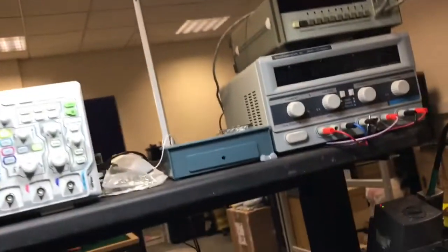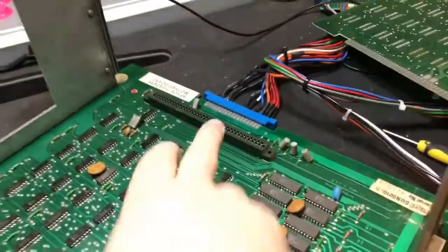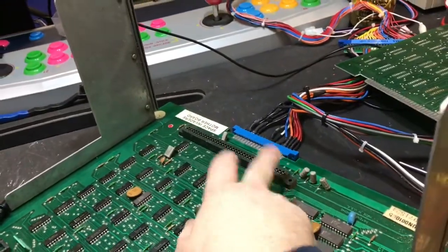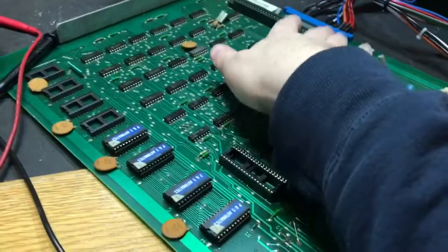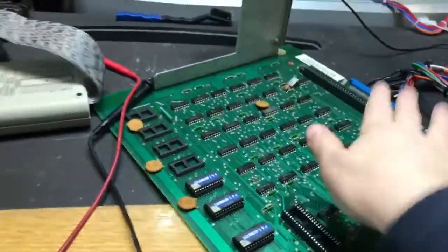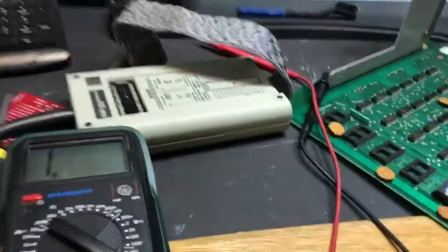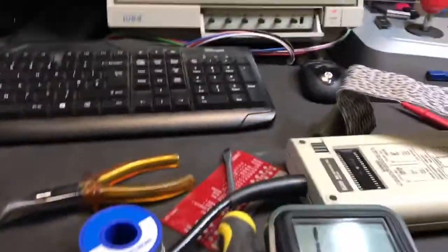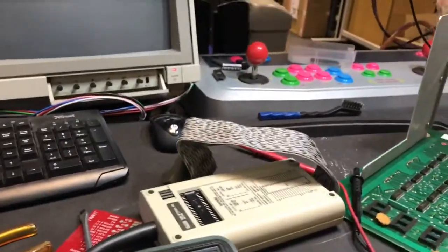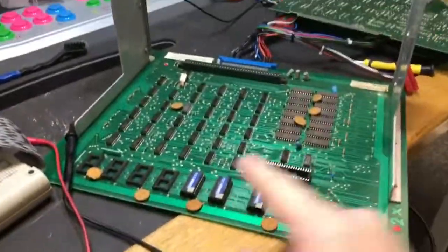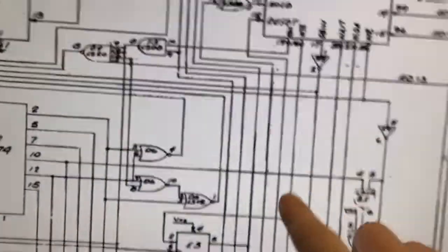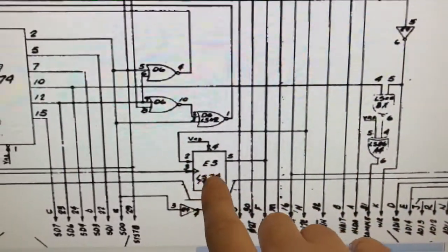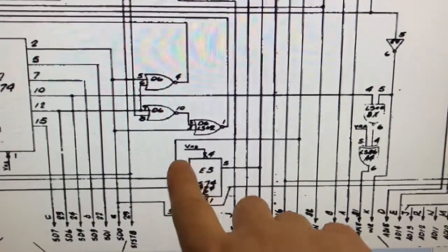So that signal is not being used, even though it's going to that edge connector, Midway designed it to go to there. They obviously never decided to implement it, unless that's a way that they could stick a test card in there or something like that for debugging purposes. That would be about the only thing I could think of. Or maybe if you tip the board on its back, you'd have a probe point directly onto that. So the INTE pin goes to this S74 chip here, E5, and it only goes there.